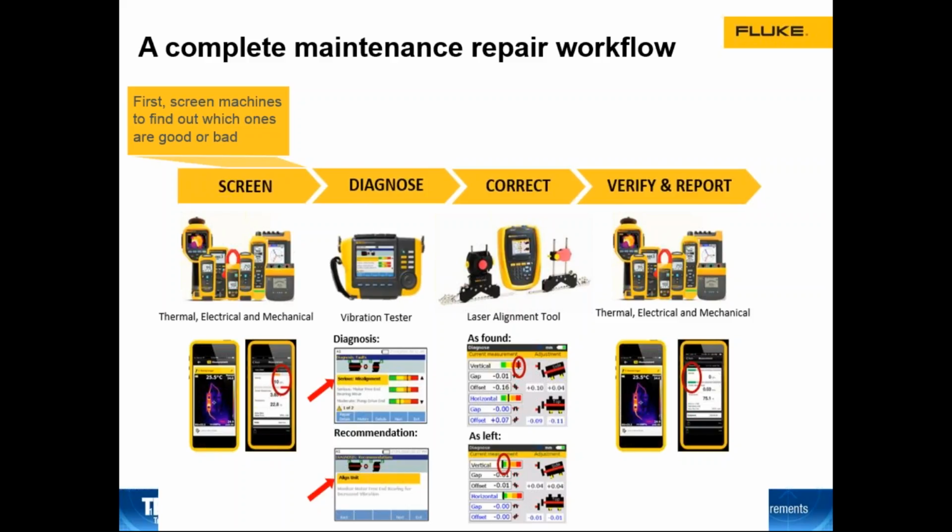If it's bad, bump it up and find out what the problem is. Then we would use simple diagnostic tools that would provide us answers, just like a doctor, and it's going to tell us what's wrong with the machine, what to do to fix it. It's not going to be able to be used on the very complex machines, but on your motors, pumps, fans, compressors, and blowers, those faults are pretty basic.